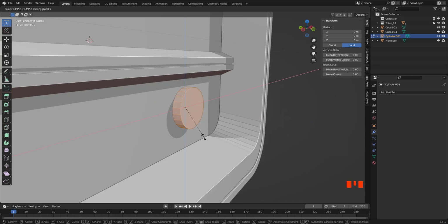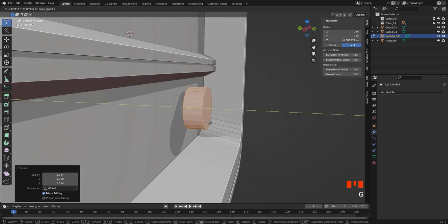If you hold on Shift Y, then you will block further scaling in Y-axis. So press S first, then repeat. As you are able to see, we are scaling in Z-axis and X-axis but not in Y-axis. For example, if you press S plus Shift Z, then you will resize it in X and Y-axis, but you will block out the Z-axis. Pull it out a bit.